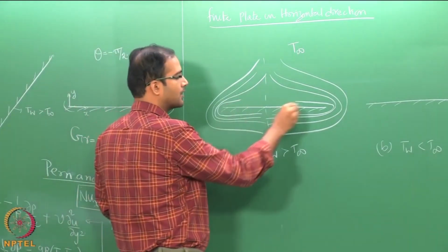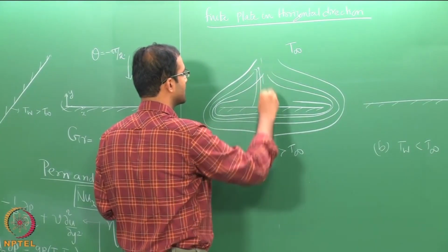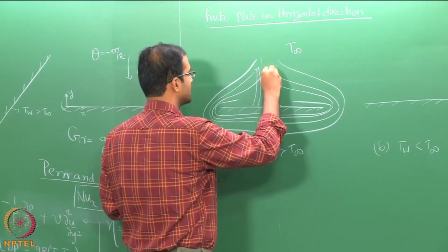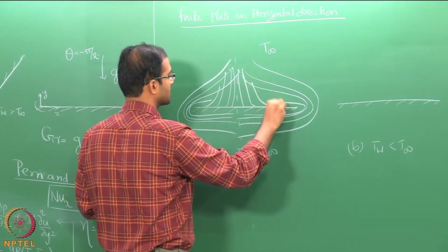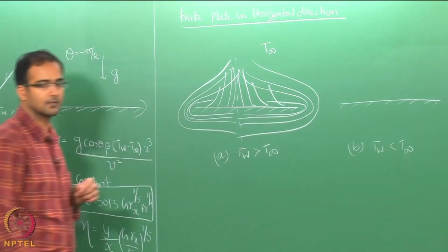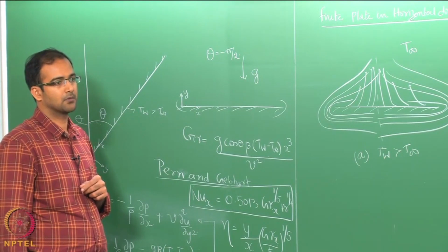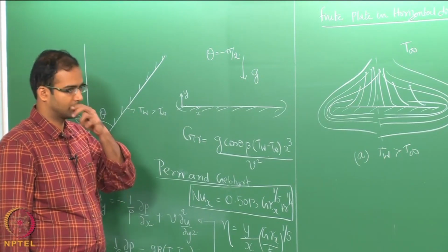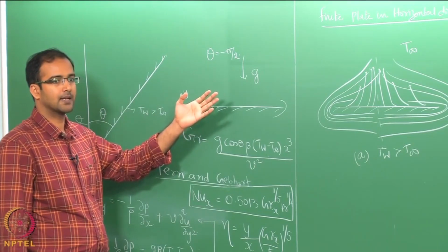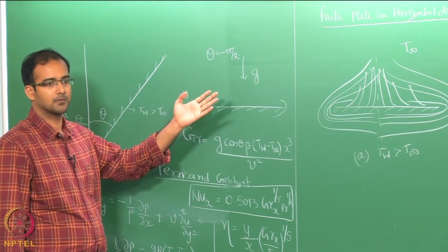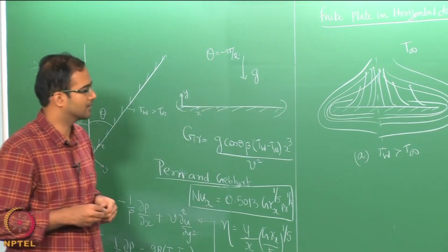And the hot fluid on the top surface, what will happen? This will also have a tendency to rise up. Correct? So, this is a very complex flow pattern that you will have. Okay. So, in this case you cannot neglect the y momentum. So, everything will become important. So, therefore, you cannot find an analytical solution.